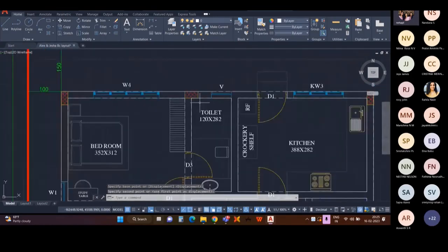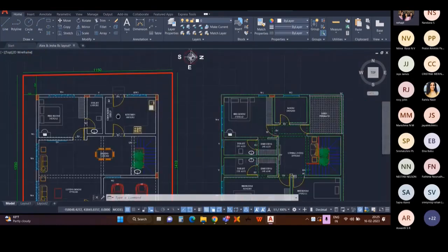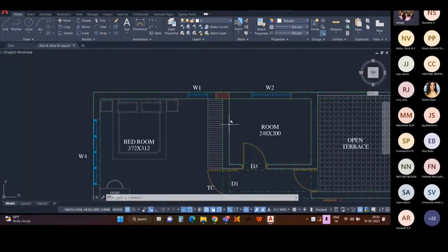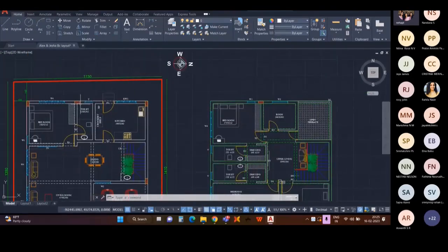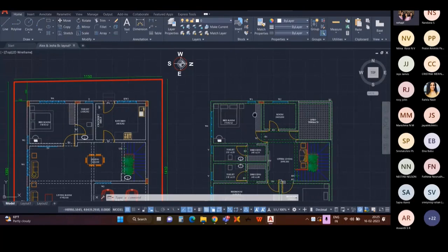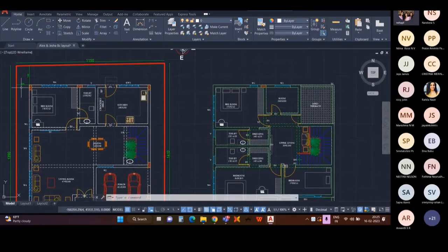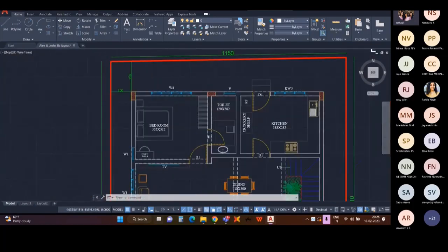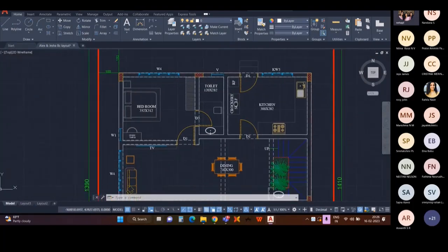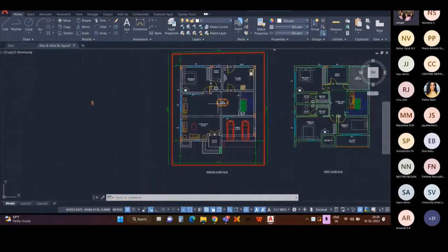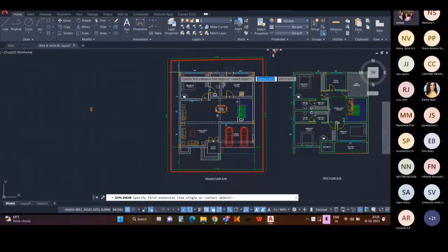Here, when we consider the ground floor, the beam is directly entering into this column, and now when we consider the first floor, this beam is directly entering into the column. So this column at the left portion has a complete connection to the beam at the ground floor, and this column at the right portion has a complete connection to the beam at the first floor. So that idea of providing a column here is okay. This place is okay because the column has a beam connection at both portions, and the direction is also safe. So we have completed this level where there are 3 columns and the distance is less than 5 meters. Now let's look at this next wall. Let's measure the dimension of that wall.